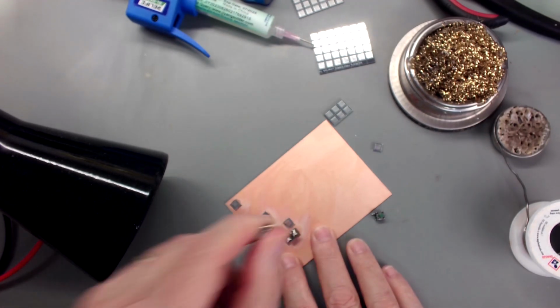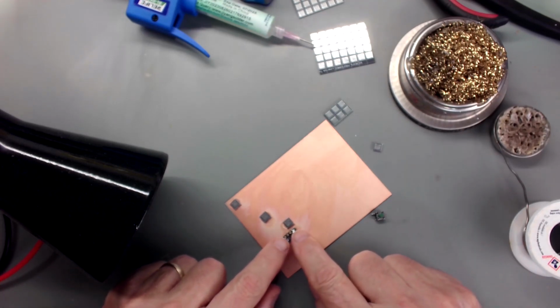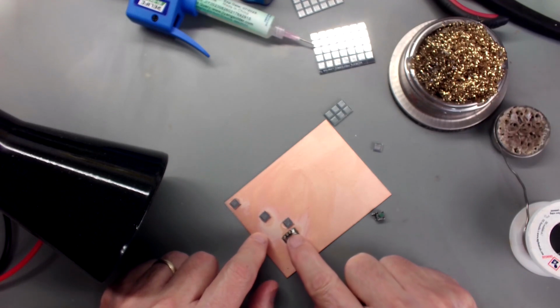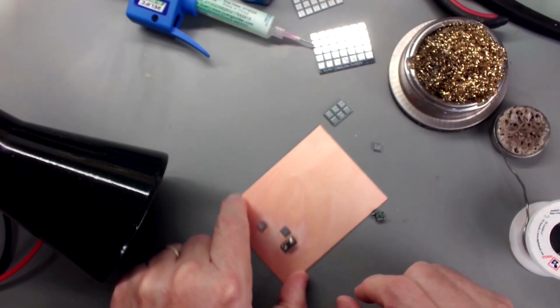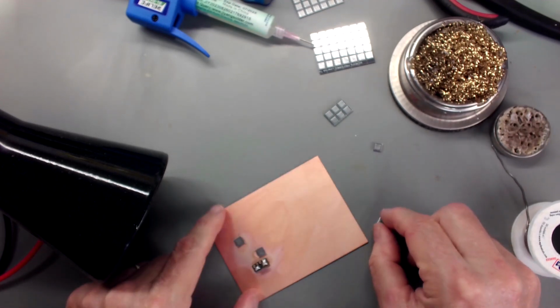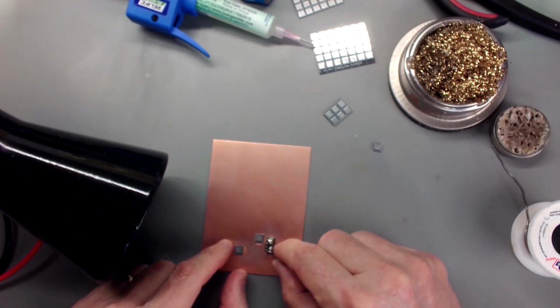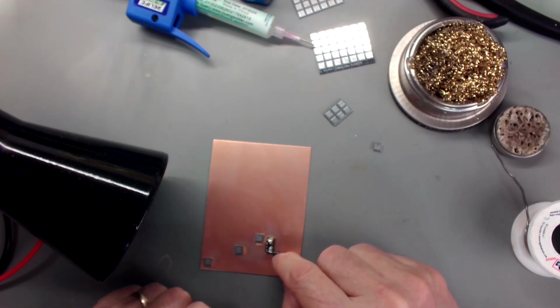So that lets you just plug it in and pull it out. So that's mounted, the 2 outer pins. Center pin's cut off short. It's not touching anything. Let me get you a little look here. So basically I'm going to take this switch and solder it onto this pad, and then I'm going to solder it to ground, and that's where we're going to ground our crystal out with.